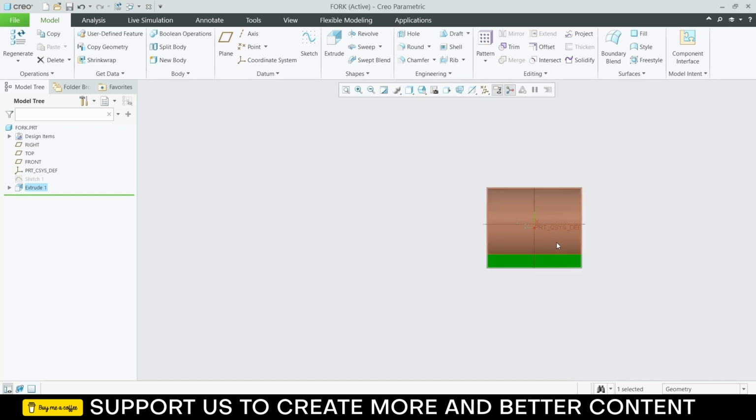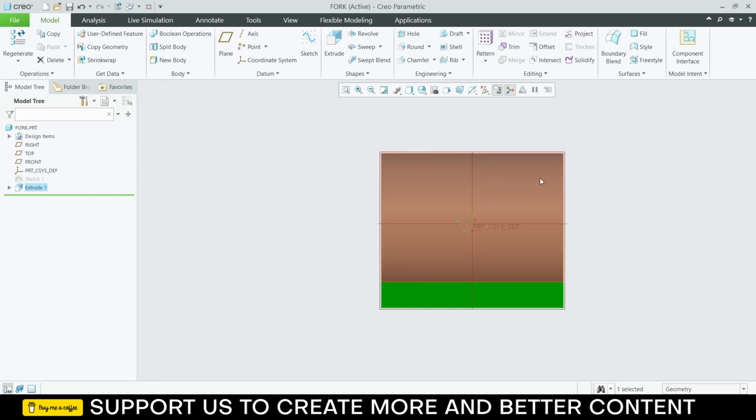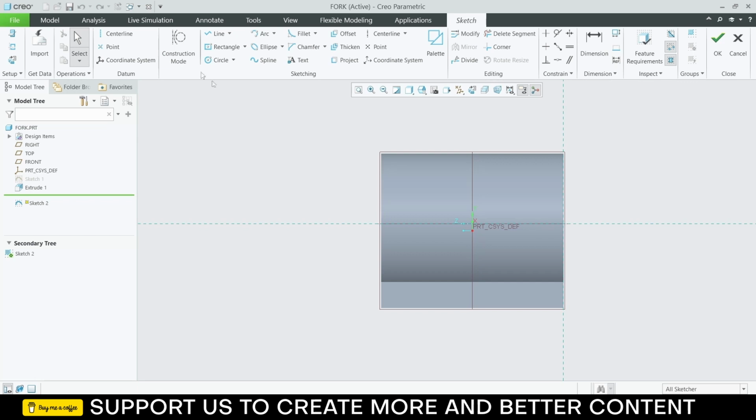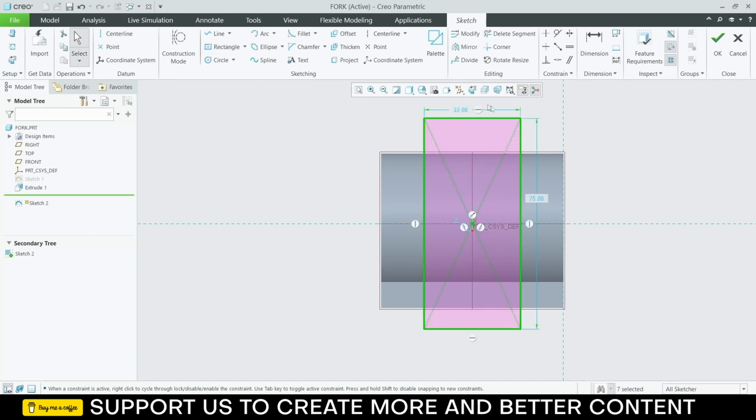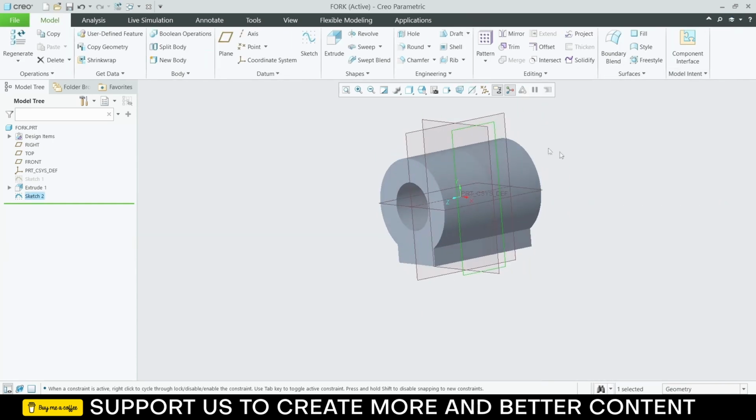Click normal to the screen. So you will see some advanced extrude feature here. So watch carefully. You will learn something new. So click on here. Basically, I want to cut a rectangle shape here. I only need to know its width. Its width is 28. Click OK.